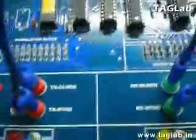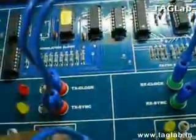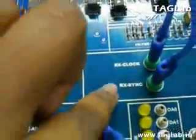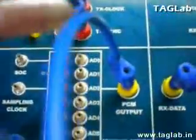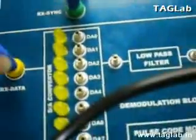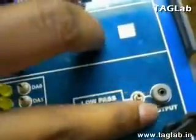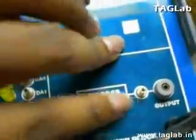Now here, firstly, you have to connect the transmitter clock to the receiver clock and the transmitter sync signal to the receiver sync signal via patch cords. And to check the demodulated output, connect the PCM output to the receiver data mode of the PCM demodulator block, and you could observe the output of the PCM demodulated wave on the CRO.